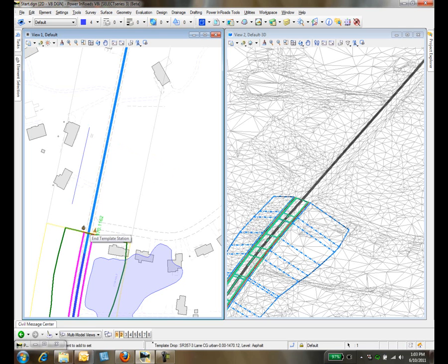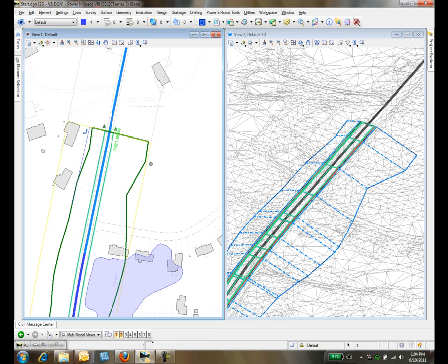Now I have a couple of ways I could do this. I could calculate the station at the end of this wall, and then I could just key in that station right here. But the problem with that is I'm limiting it to just a station, which doesn't have a lot of intelligence. A better solution would be to pick this up, and then if I want this to stop at the end of the wall, just snap to the end of the wall. So I'm just going to let AccuSnap grab the end of that wall. I'm going to accept it, and of course you'll notice everything is moved up in both the 2D and in my 3D model.